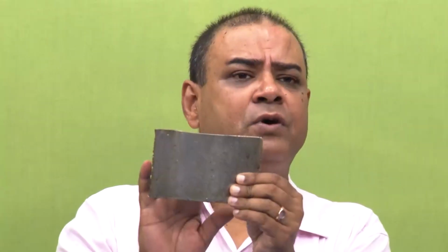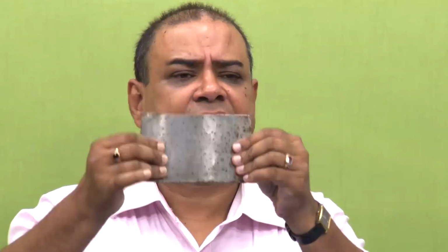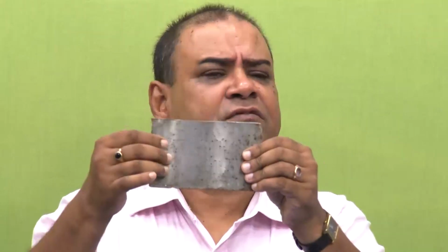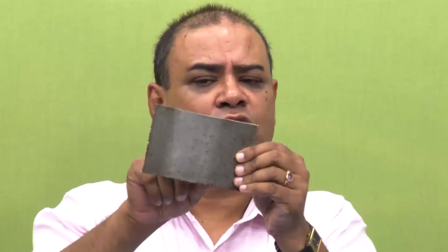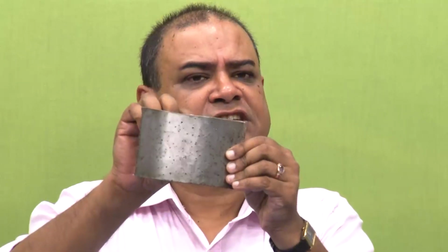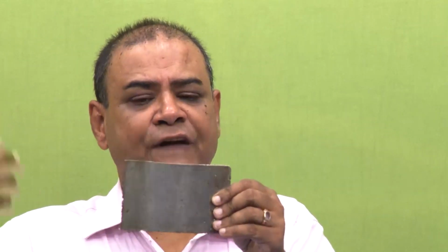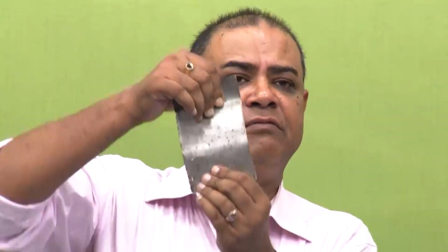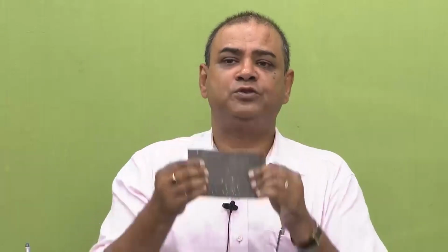So, I am just talking about a structure made of some kind of material like this, designed to hold some load. Once we have holes like this, the cross section is decreasing. The design load will be felt heavily on these smaller cross sections, and then the stress would go beyond the yield point, it will start yielding, and the situation may arise that it will crumble into pieces.